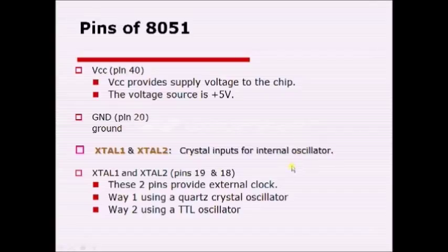Okay, and an oscillator internally contains one inverting amplifier along with some feedback element. It has to satisfy the Barkhausen criterion so that we can say it is an oscillator. Now we can design that feedback element with the help of RLC components. But if we go with RLC components, there are some drawbacks associated with them. That is why we are going with one more component, the crystal. So we are designing the feedback element with the help of this crystal. Let us see how to design that.